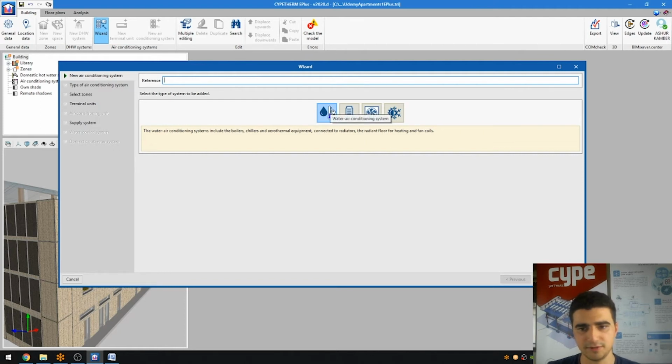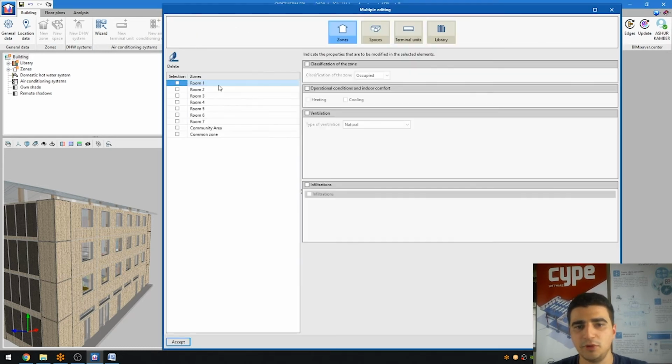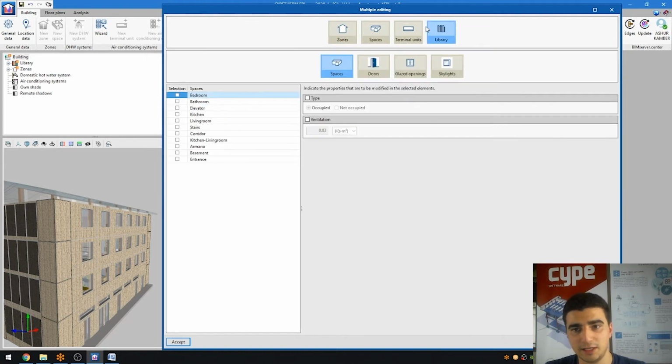So we have multiple different types of air conditioning systems. Water air conditioning system, direct expansion air conditioning systems, and also constant performance equipment. So we're going to go through this a bit later on, but just a quick overview about the workflow. Then here we have our editing tab. So we have the multiple editing so that it can fast track your editing. If you have multiple different rooms, multiple different zones that have similar characteristics, we can use our multiple editing tab to select particular rooms that we want, select them as spaces. So not just rooms, sorry. We can also multiply edit zones, spaces, and terminal units as well.